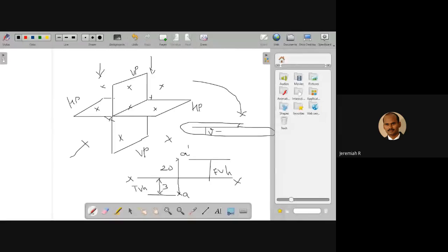So you have to draw something. This line is called the projection line. It should be very, very light. So you have to use a 2H pencil or H pencil or 3H pencil. Only this point, because we are just keeping the point. We're just projecting. So what is visible? Only the point. We are just drawing the front view and top view. So this is A dash like this.